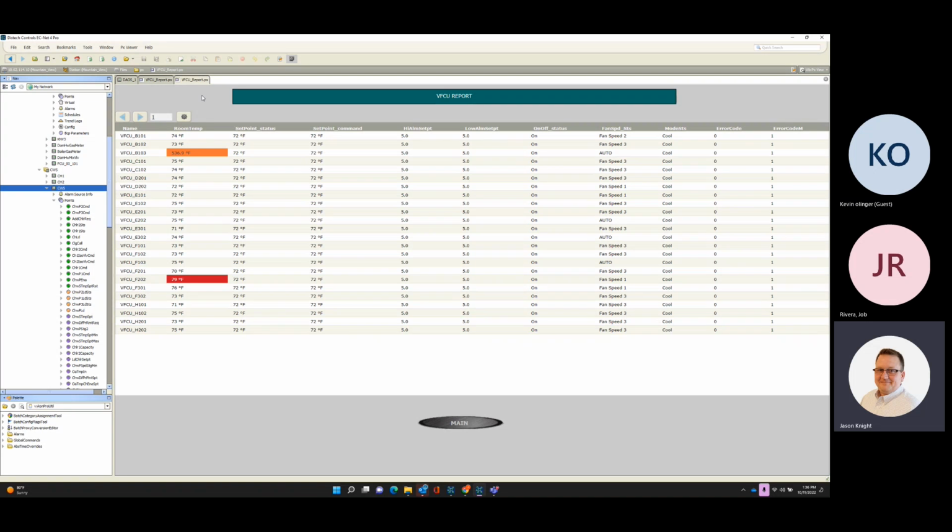it's got to be below, chill water has to be above the lockout set point, and X amount of valves got to be open, and then it goes through its startup sequence, and it has like a 15-minute on delay time, and then when it goes through its shutdown, your pumps do a 15-minute minimum run time, or 30 minutes, or whatever it was called for. Okay. But we'll go through all that when we're on the next training. The chill water plant, hot water plant will be a whole day by itself.